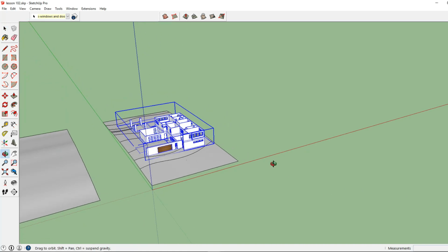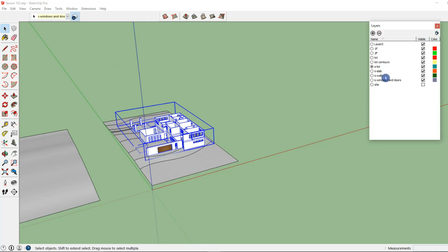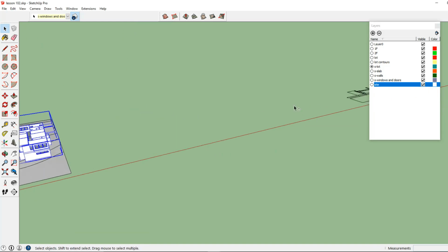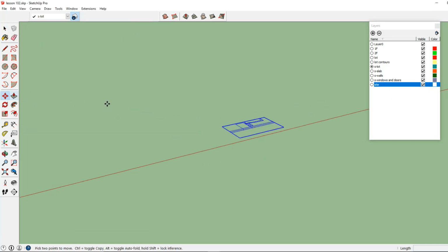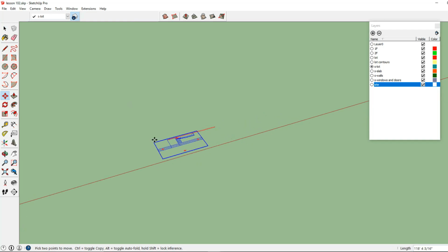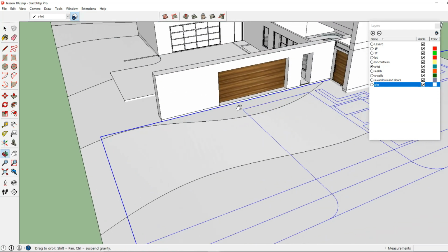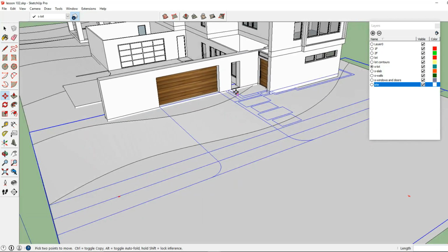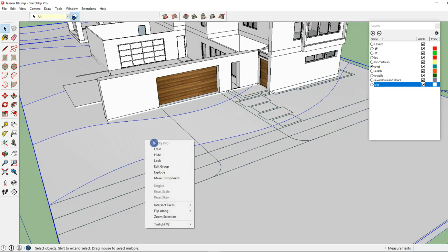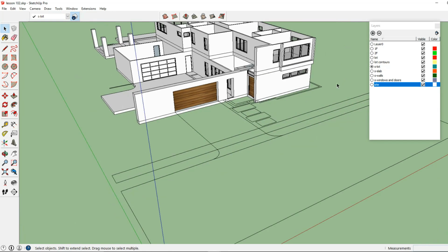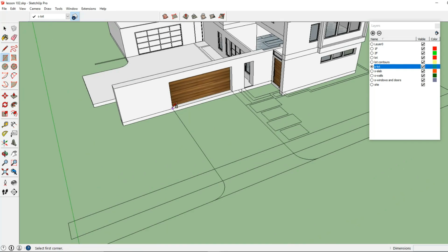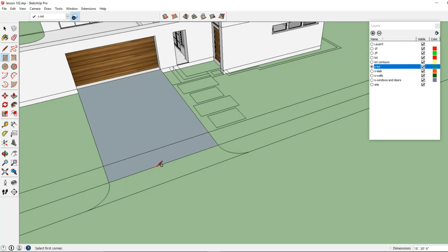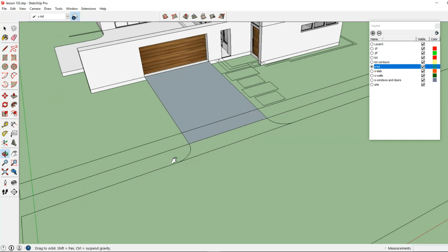Now let's create surfaces from our site plan that we brought in from AutoCAD. Let's go to layers and turn on site. And here we see it over here. I'm going to drag it from one of these endpoints here on a driveway and line it up here. I'm going to turn off my terrain for now while I model this. I'm going to make this S-Lot layer my active layer, and let's create surfaces from this CAD plan.